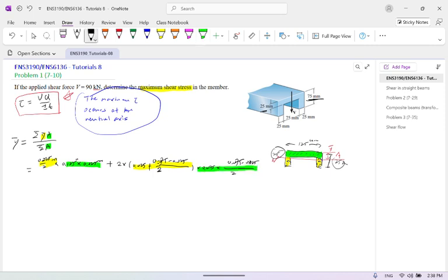Okay, so I'll show you for this. Divided by 0.125 times 0.025, plus 0.025 times half of the 0.075 minus 0.025. This is from the structure. So that's what we can work out: 0.029167 meter. That's the Y bar from the top. Okay.